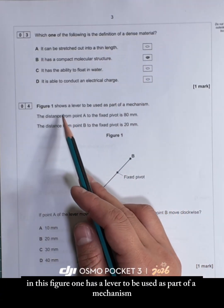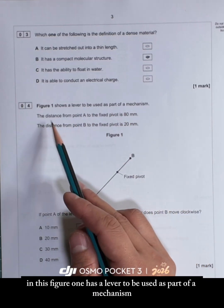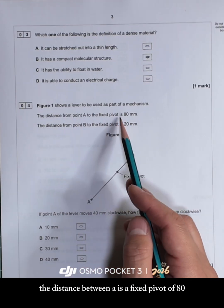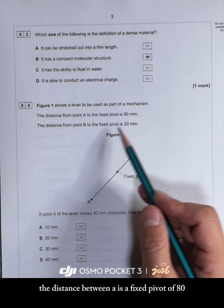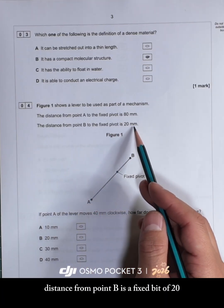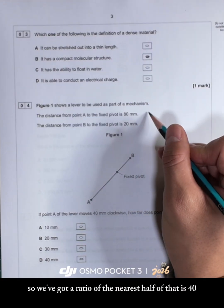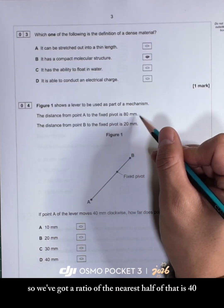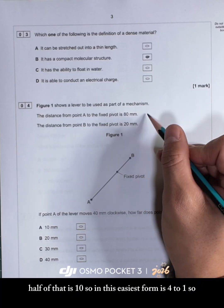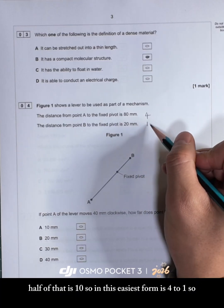In this, figure 1 has a lever to be used as part of a mechanism. The distance between A is a fixed pivot of 80. Distance from point B is a fixed pivot of 20. So we've got a ratio of the nearest, half of that is 40, half of that is 10. So in its easiest form it is 4:1.